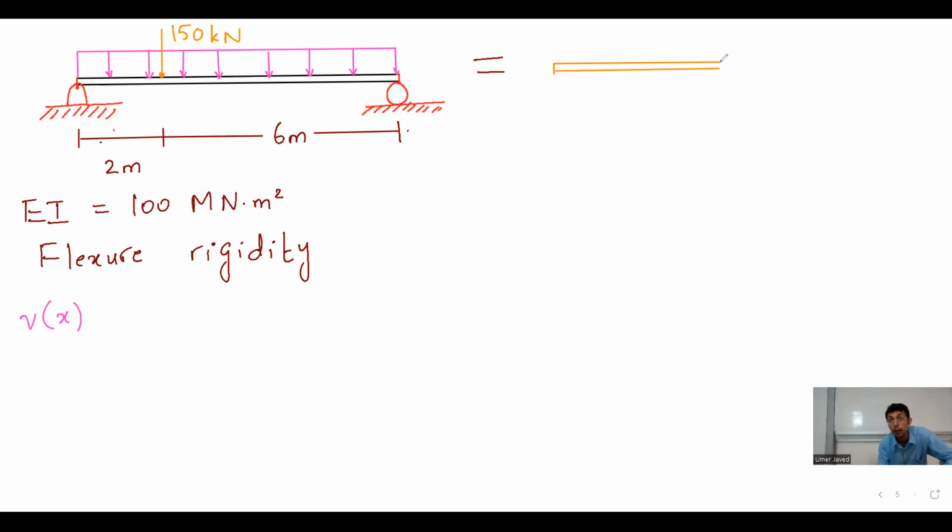Yes, Usman. What is the W value? What's the distributed force? I did not tell you, right? Oh, 20 kilonewton per meter. Good question. Sorry, this is my mistake. It is 20 kilonewton per meter, because the beam manufacturer told me that because of the weight of the beam itself, it is 20 kilonewton per meter distributed over it. It is an unloaded beam, and now I put 150 kilonewton on top of it. This is equal to this plus...